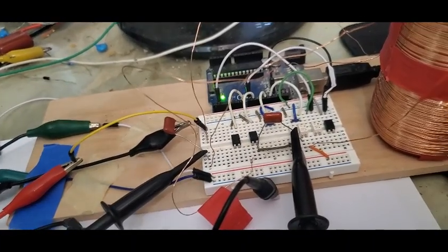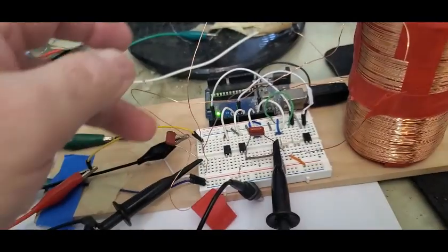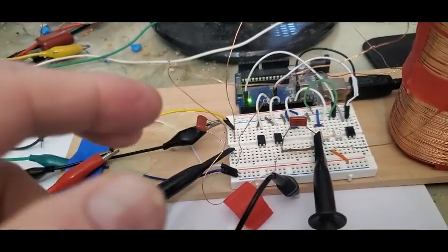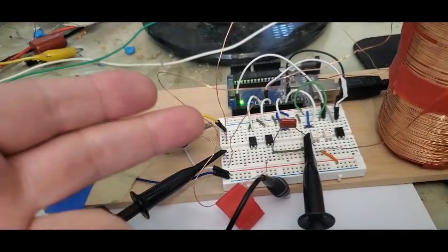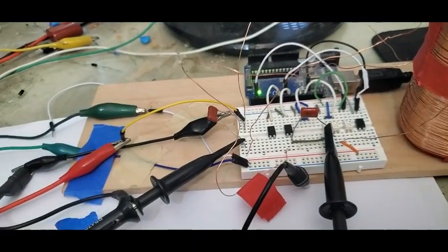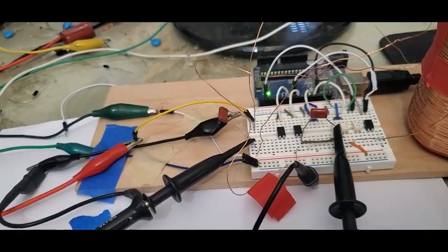That's what the cool kids do. They can switch down to like microseconds. I can't do that and stay opto-isolated, so I'm not going to worry about that. There's a couple of real simple ones that I haven't tried. One is, what if I just put in a resistor between this ground and this ground? So I'm going to try that, and I'll get back to you and see what that does.